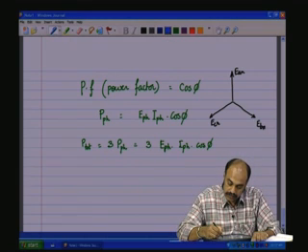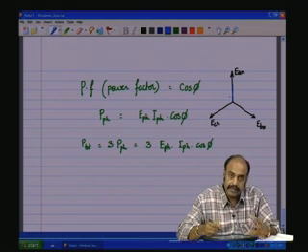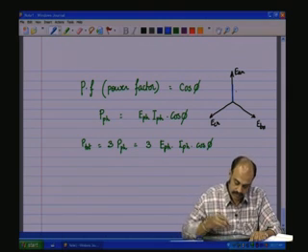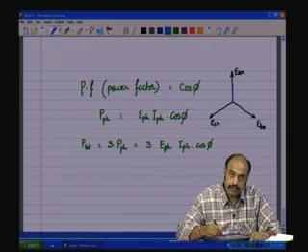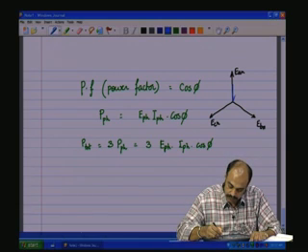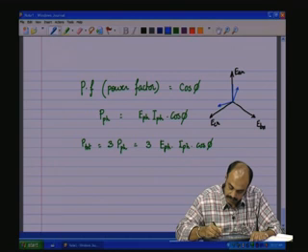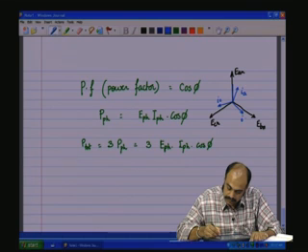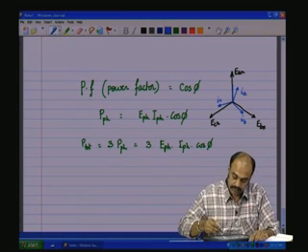In a resistive network, the currents are going to be in phase, but in the case of, let us say, an inductive circuit, RL circuit, which is there in the three load arms, you will have a current which is lagging each of the phases. So, this would be IA, IC, this is IB.